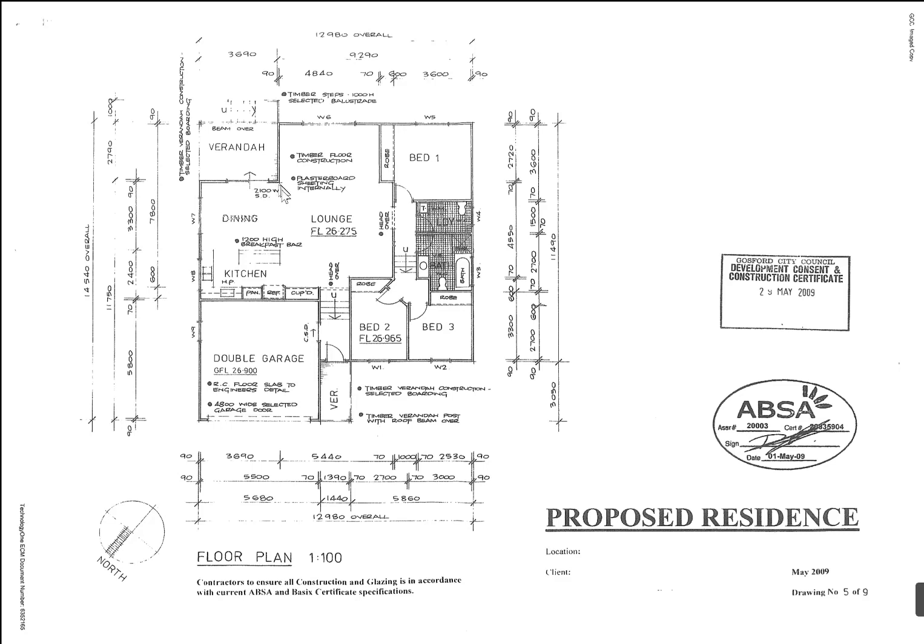Here the code would probably be SD2121, because normally the sliding doors are 2100 high and here it is 2100 wide. If, for example, this was 1800 wide, my sliding door code would be SD2118 to indicate 1800 wide and 2100 high. In any event, that changes from manufacturer to manufacturer.